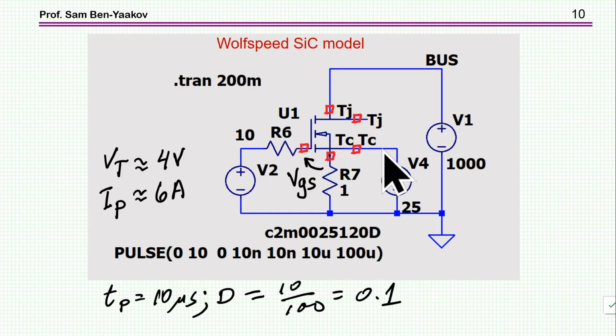So this goes directly to this clamping temperature. Of course, if I had a heatsink and I knew the thermal resistance of the heatsink, I could have put a resistor here, okay? But in this case, I'm just examining parameters against the data sheet, and most of the parameters in the data sheets are given for a case temperature of 25 degrees or some other.